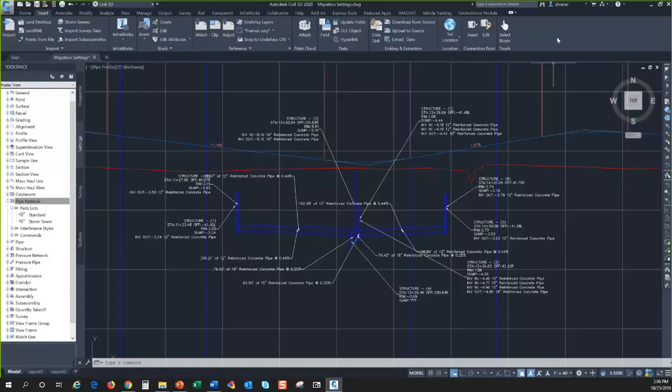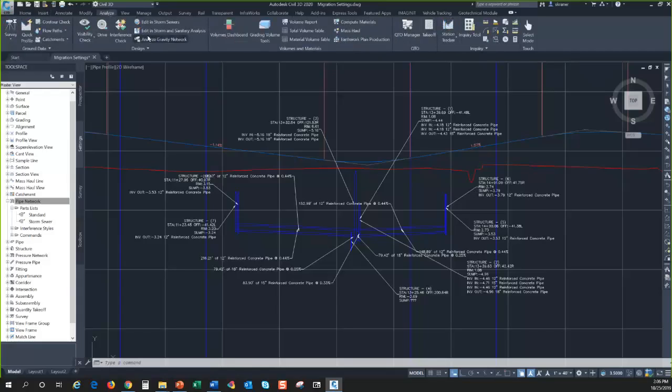As a matter of fact, there are some tools within Civil 3D. Analyze Gravity Network, which is a little limited, but it's a good tool for doing some calculations within Civil 3D. And I believe that Randy did a piece on that not too long ago that showed you how that could be very useful. So I'm not really sure what form he would want those calculations to be in an XML file. To me, the XML file should contain the changed pipe, invert, and sizes, and I don't know why to take it out. We'll take one more question.